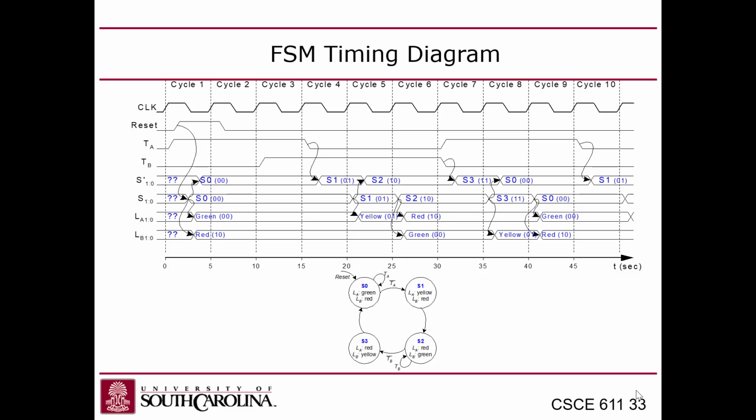The dotted line signifies the rising edge, but yet the state doesn't change right on the dotted line, right? Because they're trying to show that there's a little bit of a propagation delay before the state will change, because the flip-flops are not instantaneous. They don't change immediately on the clock edge in reality. But Model Sim will have these things changing instantly, right? Because Model Sim doesn't have any notion of propagation delay. Okay, so that part, at least, I found confusing.